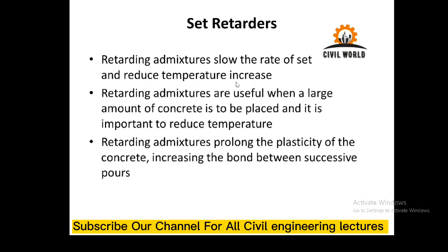And then one of the major advantages of its use is when concreting is performed in different layers. So to avoid the setting of the already placed layer before the next layer is placed, and to avoid cold joints, set retarders are used so that once the next layer is poured, the already placed layer is still in plastic form, and there is better bonding between successive concrete layers. So set retarders are quite advantageous in this type of construction.